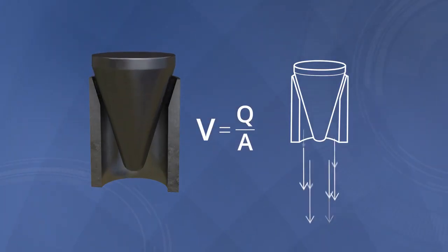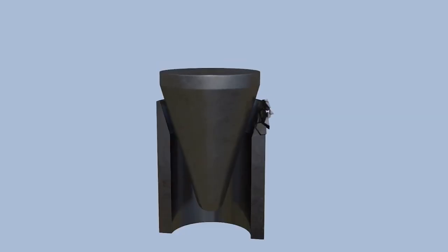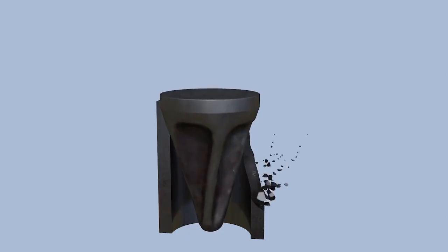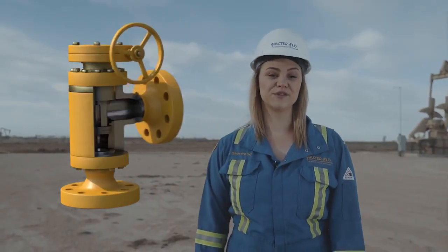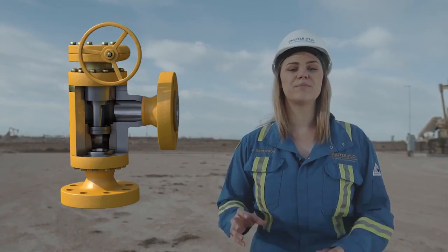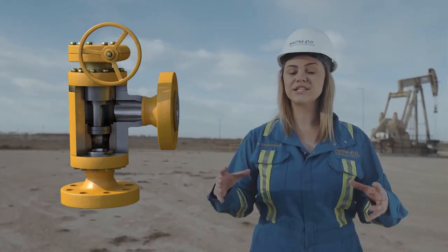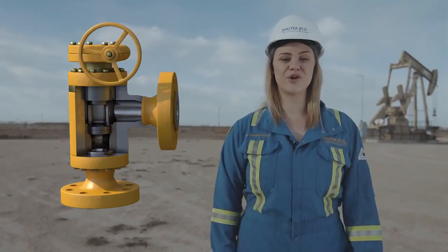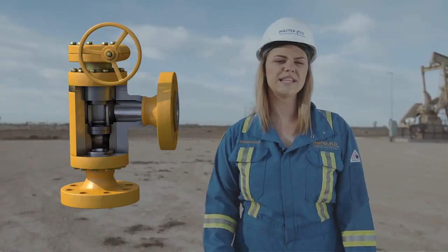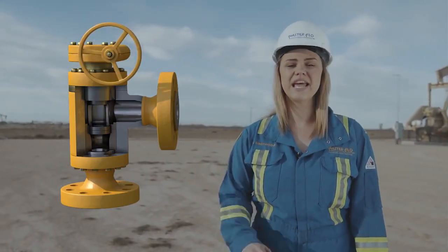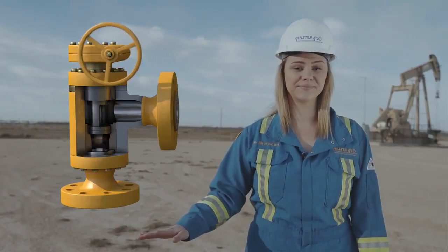The seat surfaces act as restrictive devices, which subjects them to a higher friction and deterioration. Multiple orifice valves, or disc-style choke valves, provide improved flow control and shutoff capability. When these openings are perfectly aligned, the flow rate is maximum. When these openings are offset by 90 degrees, it shuts down the flow completely.